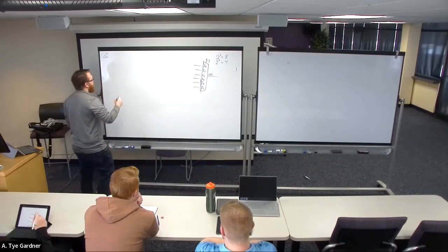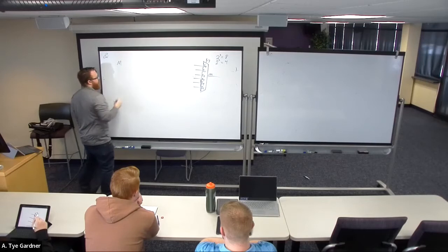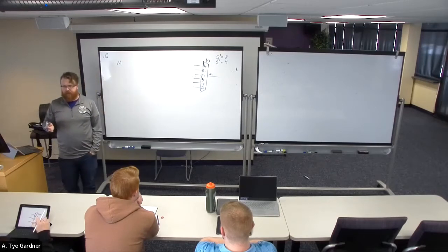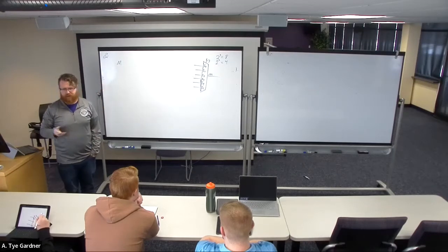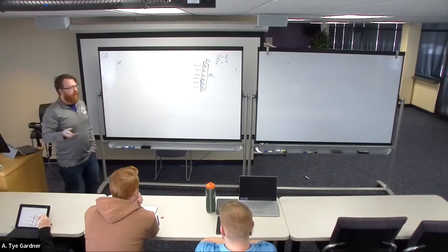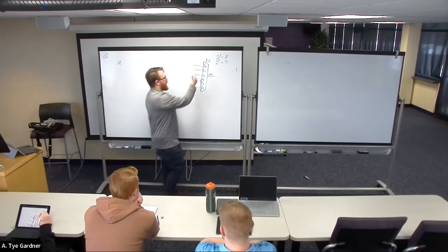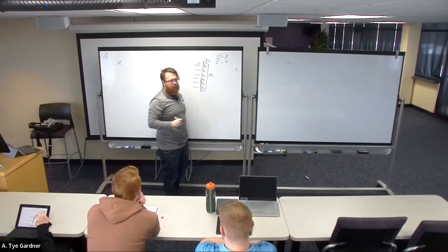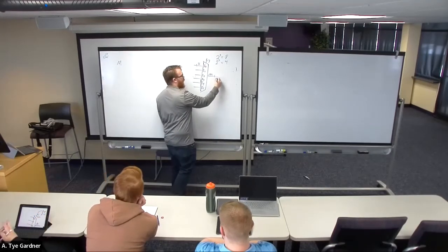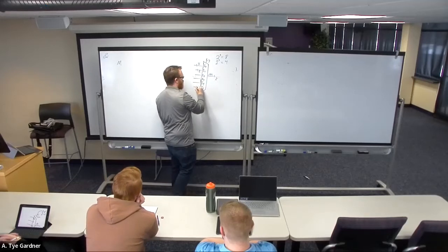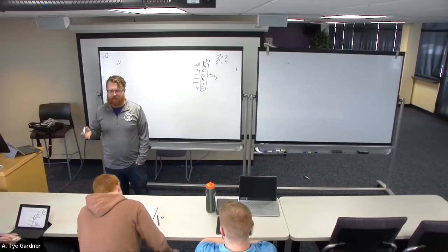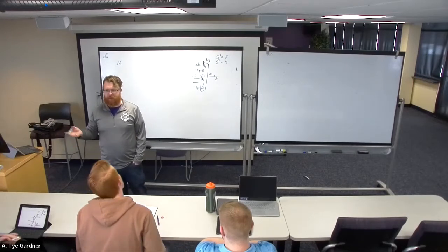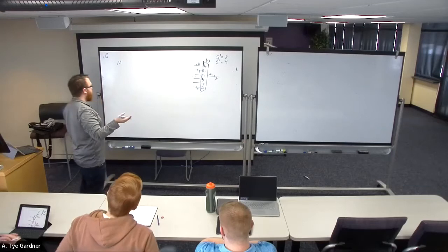Well, the way I write this, rather than doing a truth table, because that would be a nightmare, right? Because I would have a 3-bit select signal and 6 inputs. And if these are suddenly 8-bit inputs with an 8-bit output, right? Now it becomes a bit of a nightmare. You could never do that truth table. It becomes impossible, right? So we need a different way of designing it.